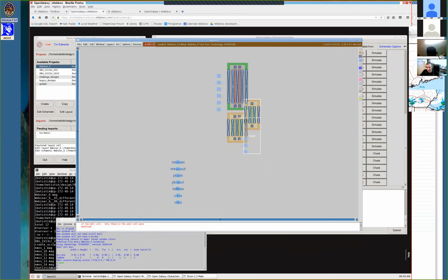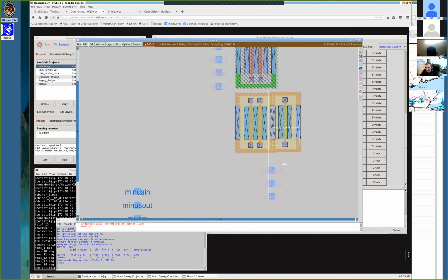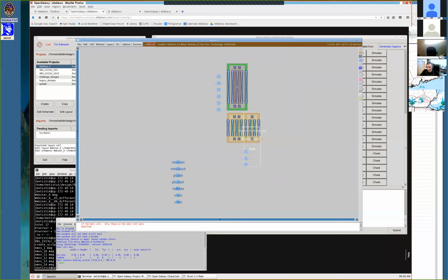If I type Control-I twice, I get the whole circuit, and since that subcircuit is within the edit cell that I'm doing, I can move the whole subcircuit. So again, with the hierarchy here, I can move this around with the keypad until I match up those devices, and now I'm DRC error free. So that's how you manipulate the layout of a hierarchical structure. If you had hierarchy in your schematic, it will end up in your layout.